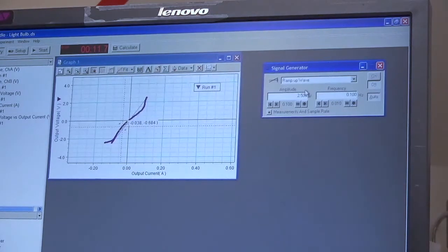And if we have a constant change in temperature, the resistance of that light bulb is going to keep varying, as we have seen during the theoretical part explanation. So the temperature and the resistance are related to each other. If the temperature keeps fluctuating, the resistance is going to keep fluctuating as well. And in that case, we have a non-ohmic device.